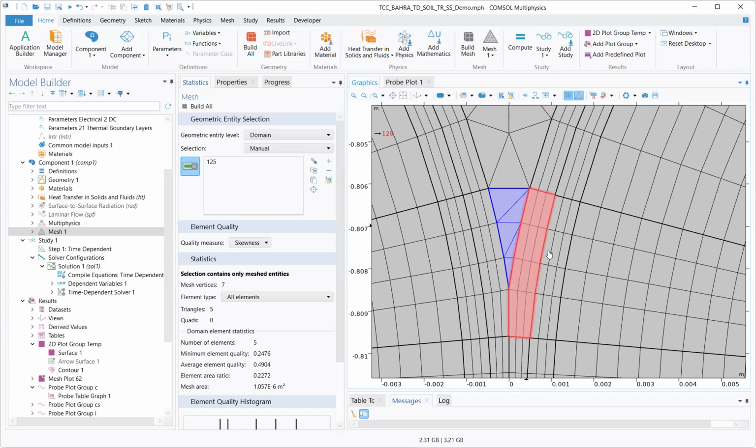But because this is a cable in soil, with no fluid, I just have to mesh. I don't have to put in a boundary layer. In other words, in a purely conductive model, with no convection, the mesh is always better. Once we involve convective heat transfer and fluid flow, and we have boundary layers, those boundary layers always reduce the quality a little bit to some extent.